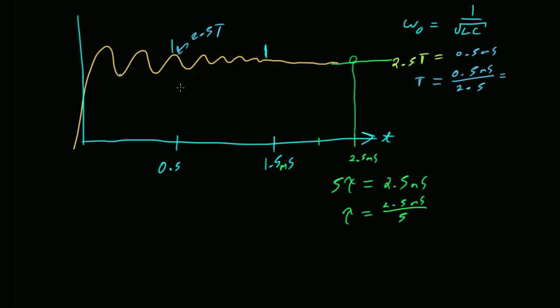Except we changed the circuit around a little bit, right? Instead of having series, it's like partially series, partially parallel. So you have to derive a new transfer function. But that's the name of the game, right? If I show you this and I say pick Rs, Ls and Cs that give you that, you should be able to get something pretty close. Maybe you're off a little bit. You say, oh, my resistor is a bit big. Maybe I should make it a bit smaller or bigger. But you should be able to get pretty close without too much drama.